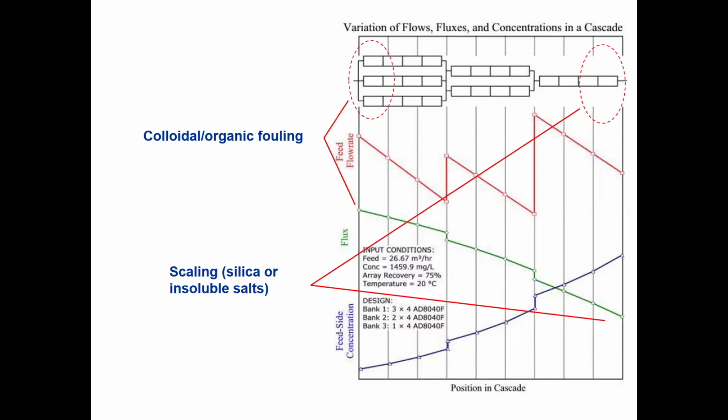Pure water is passing through the membrane, so only the water is removed, and you have a relatively higher concentration within the water. So the water that goes through the last membrane is the brine, not the permeate. Right, permeate is the filtered water. Oh, so that's why. Okay, I get it, thank you.